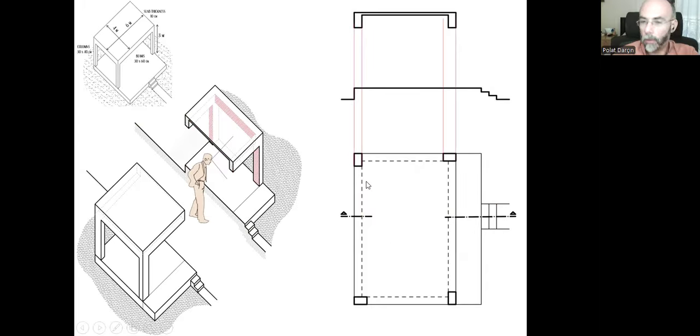So we can do one more guiding line, marking the width of this column. Here it starts from here and goes upwards, and the other one starts from here, goes upwards, the inside surface of the seen surface of the column, and do the same for the other column here, go upwards like that. And we have the beam here.